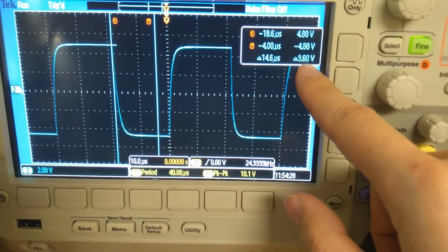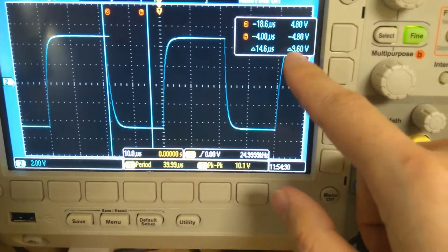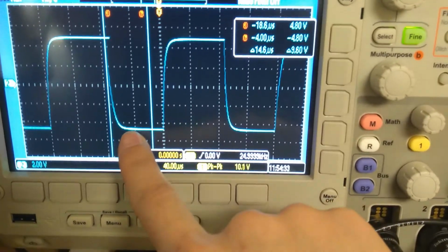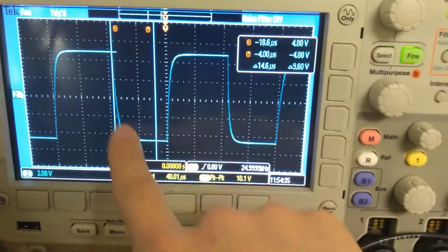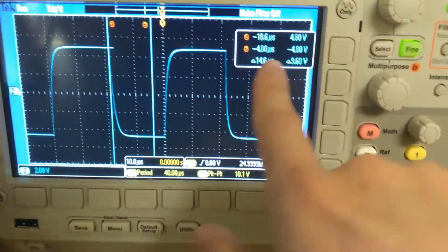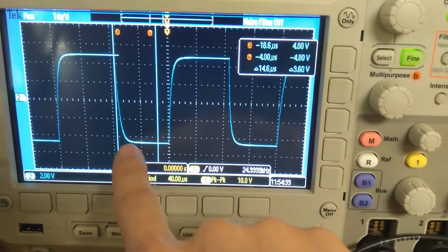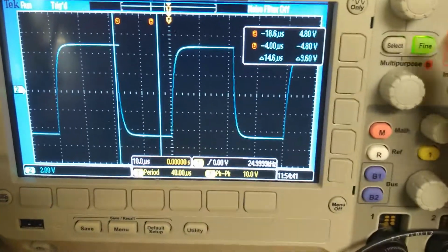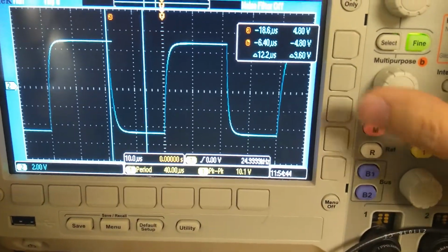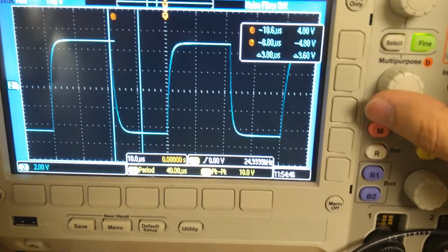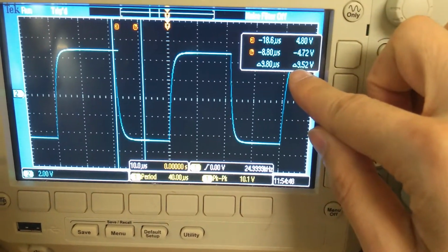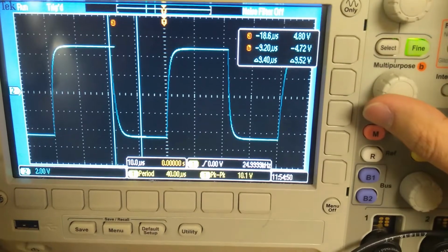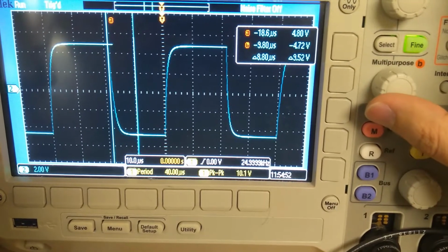So what we need to do is to find out the first time point the discharge voltage reached 9.6 volts here. So we move the cursor to the left, and we look at this number here until it starts decreasing.